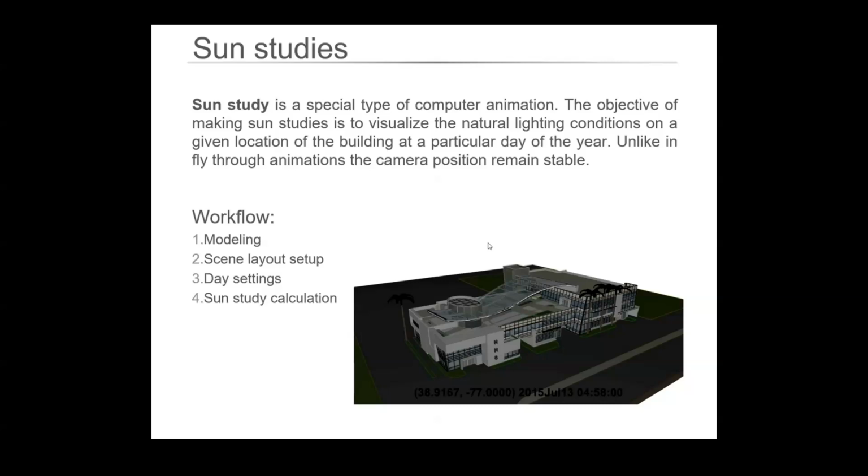So if you're in the winter, say the middle of the afternoon, and you want to see the worst effect, you can create a one-off photo, or you can again create movies, so you can see the shadow moving throughout the day, and by adjusting the time, you can make that nice and slow or really quick.